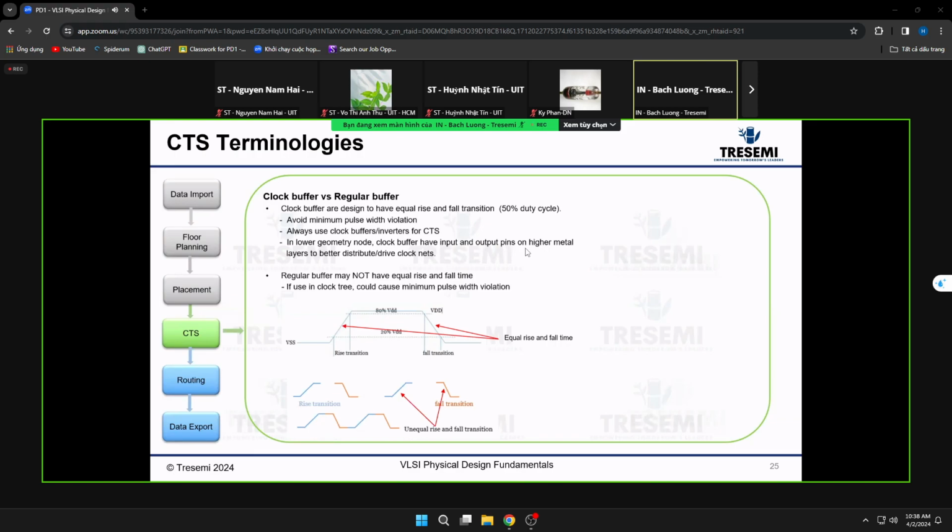In the clock buffer, usually the P transistor is much larger than the N transistor. If you understand the physics, the N transistor has electrons, which have more mobility versus the holes on the P. The P mobility is less, so the transistor has to be a lot bigger.